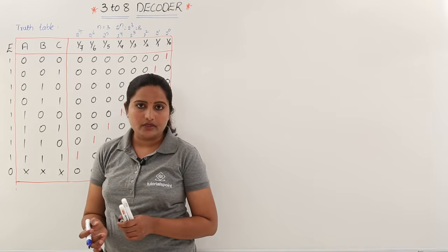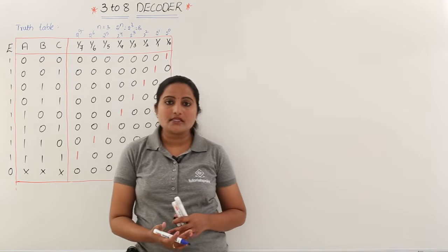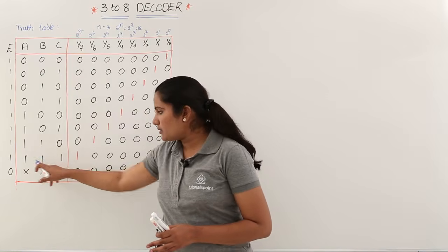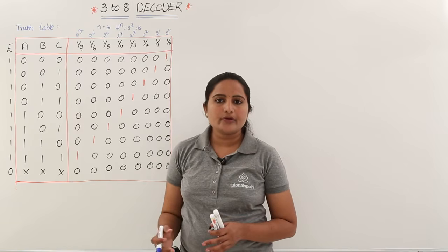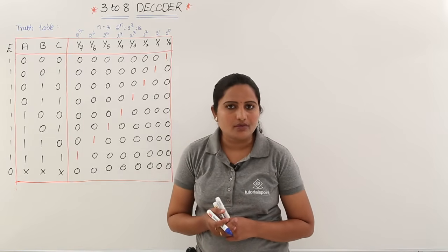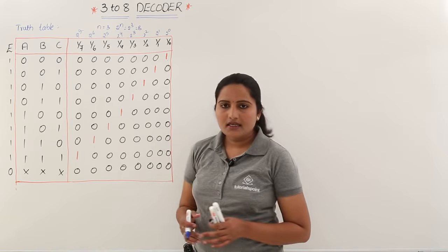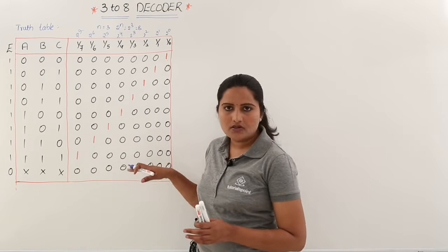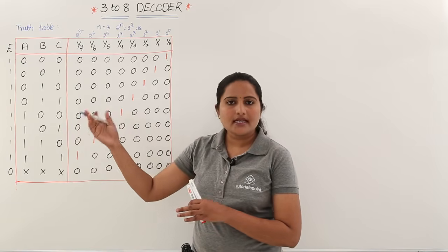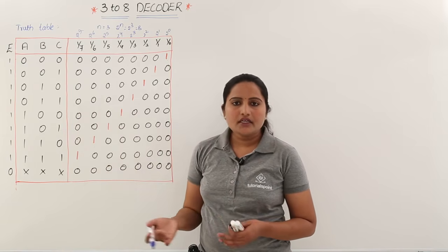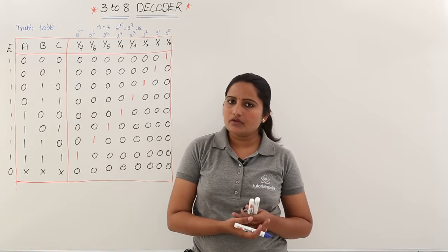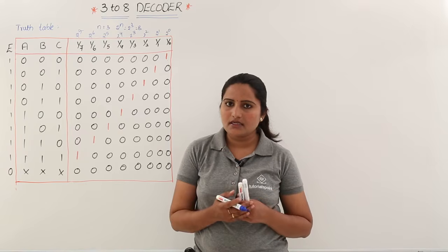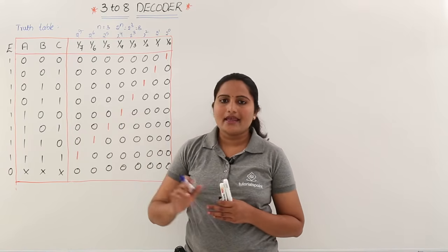This is very important. In exams like GATE they may ask it like this: for a decoder the input is 111, what is the output when enable is equivalent to 0? The options will contain 1 and 6 zeros, or 7 zeros, and all zeros like that. How do we decide? It is based on the enable line.